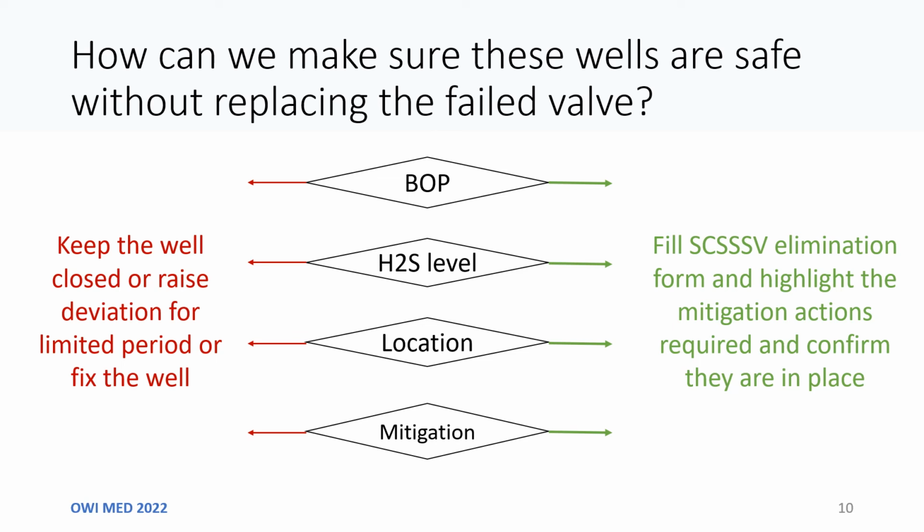Finally, we check the mitigation actions. That includes increasing wellhead integrity test frequency to make sure that the valves are operating, weekly measurements of methane leaks and H2S at the well location, constructing a fence around the wells, and confirmation with the studies team that the well will not have any increase in production potential that could make it exceed the limit blowout potential. In addition, we confirmed that we have a contract in place with a company that can cap wells for well control purposes in case the top event happens.